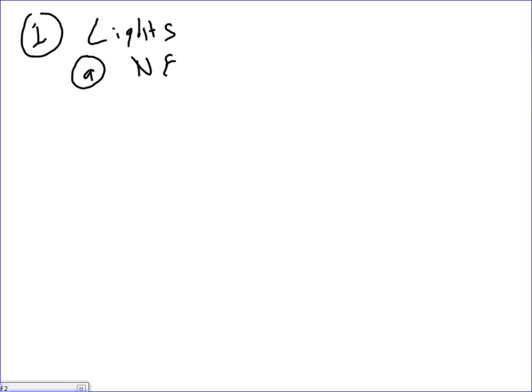Okay, what I'm going to do, guys, is follow step by step, 1, 2, 3, and do my calculation. I'm going to start with number 1. And what was number 1? Anybody remember? Lights. For lights, my friends, in the NEC code book, I'm going to do 2 calculations. A, the first one, is from NEC 2011, and the article is 220.12. It's a table.